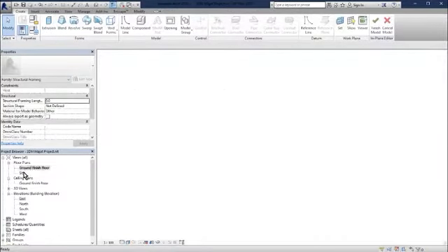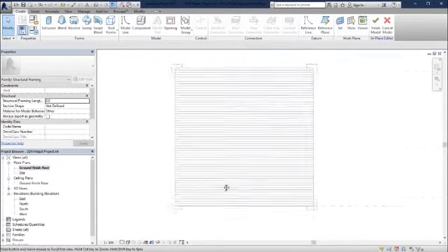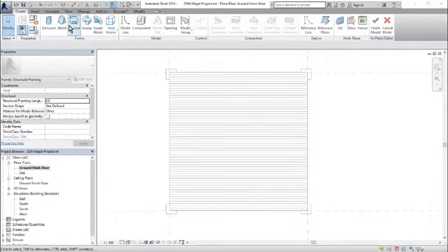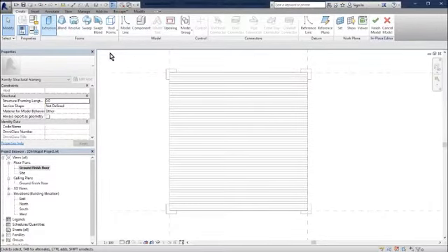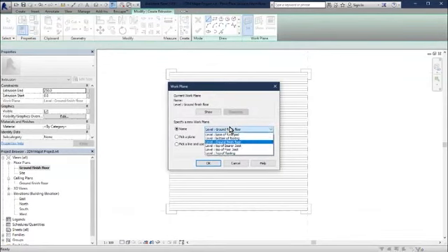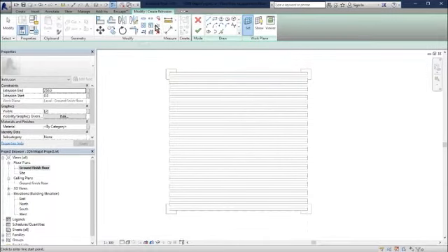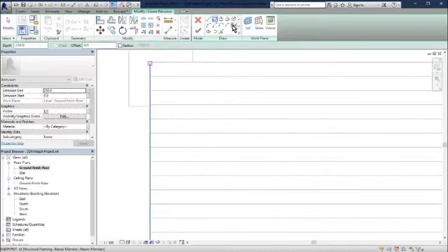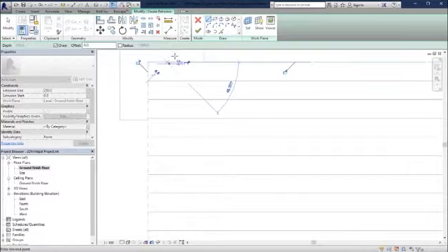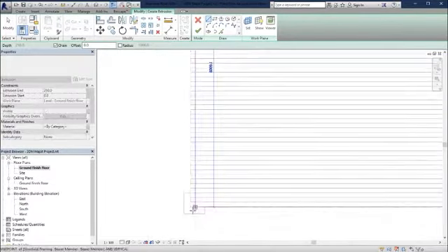and let's go to the top view to do this. And what we're going to do is we're going to do an extrusion, right? And we're going to set our ground plane as the plane that we're going to draw on, and of course we are going to go across by 100 and go down.